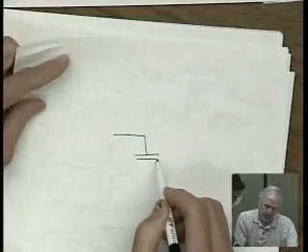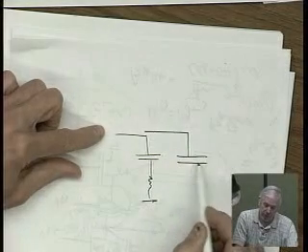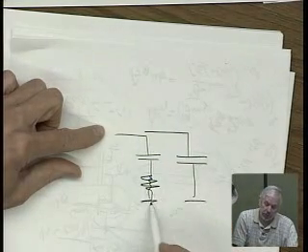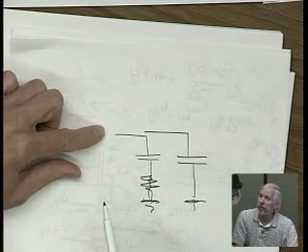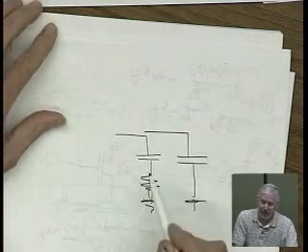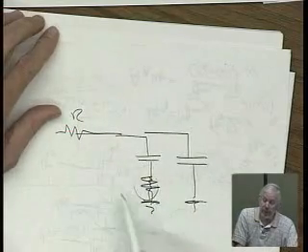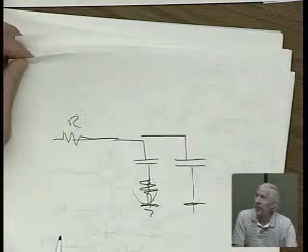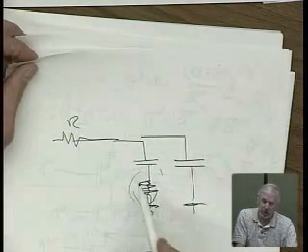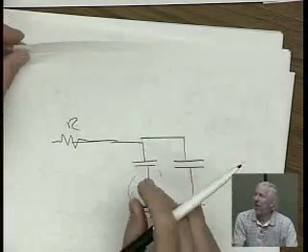In effect, what happens is, you got this case, right? You got a bunch of capacitors that are connected to ground, and you got one that's not. It's connected to a resistance. So the question is, what's the pole associated with this little network? There's actually a pole zero thing going on here. There's a zero in there? Yeah. So it's complicating things.